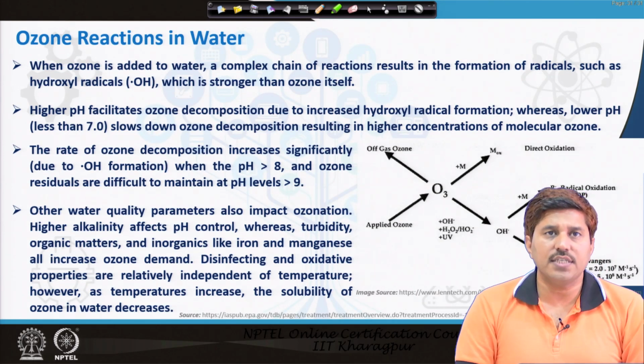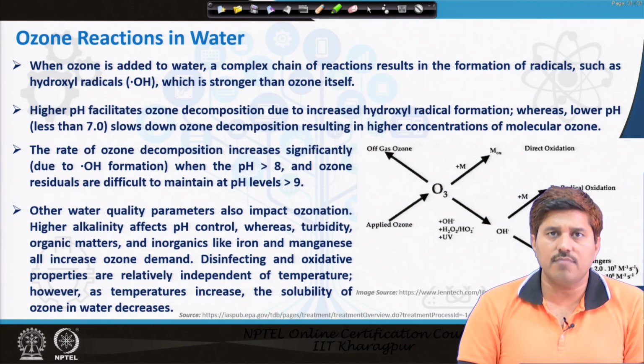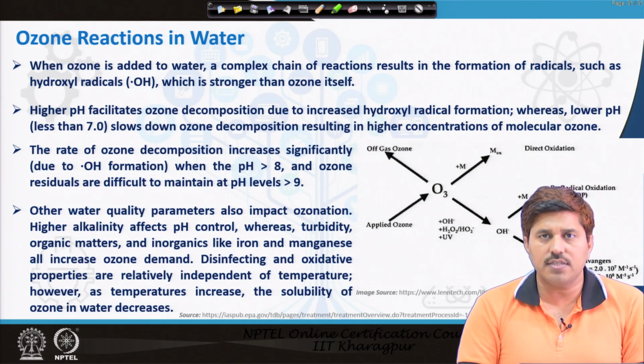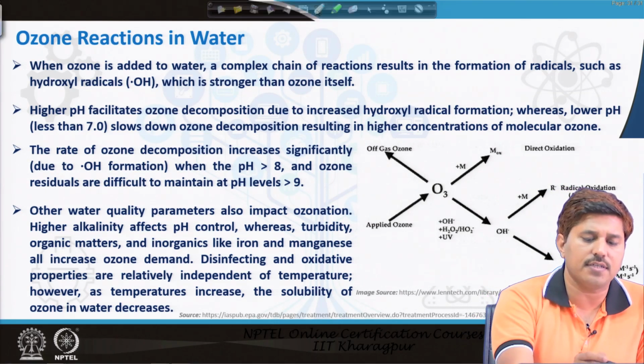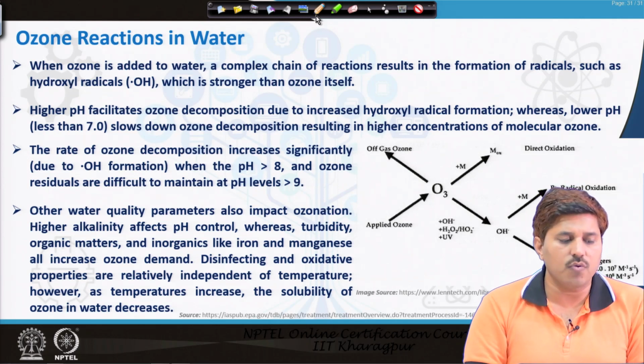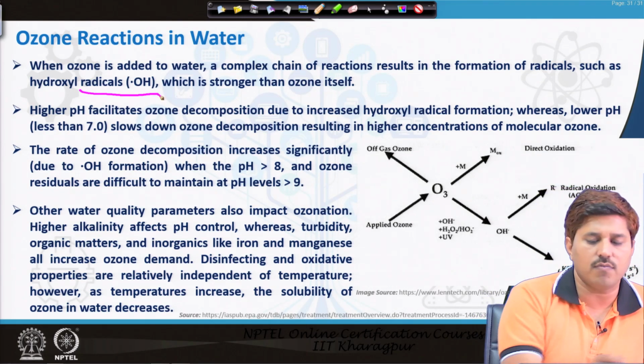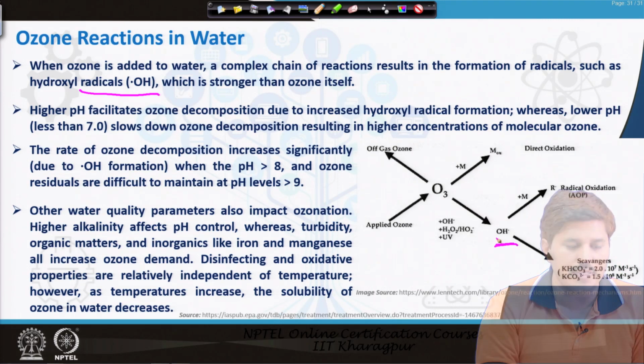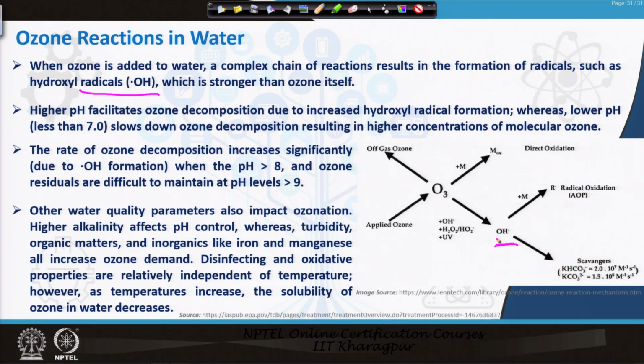If you see the ozone reaction in the water, when ozone is added in the water, a complex chain of reactions results, and different radicals can be formed. The OH radical or hydroxyl radical is one of the most reactive and most common, but many times H2O2 is also added alongside, so that a stronger oxidant can be formed at times. So the hydroxyl radical is stronger than ozone itself. The higher pH facilitates the ozone decomposition.